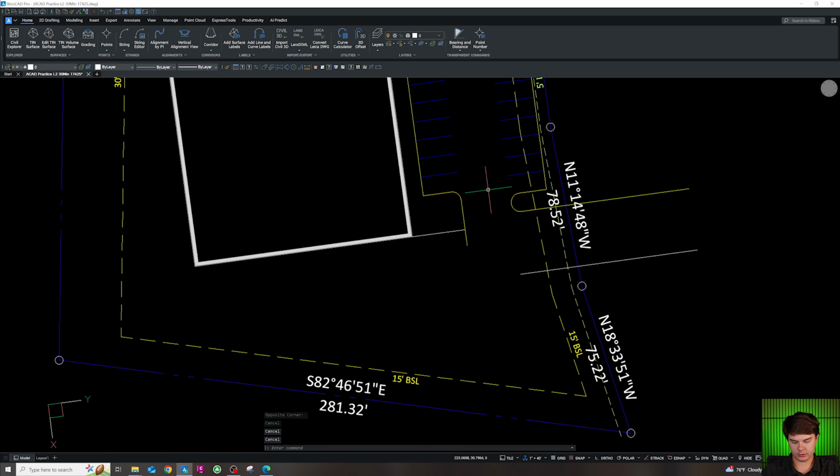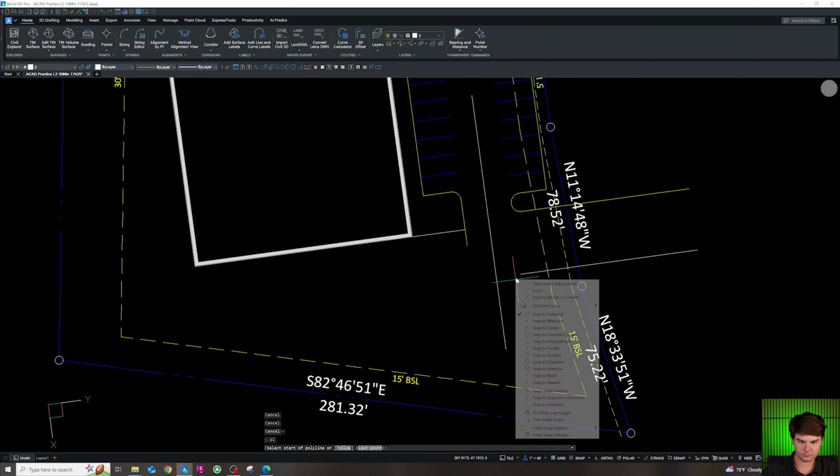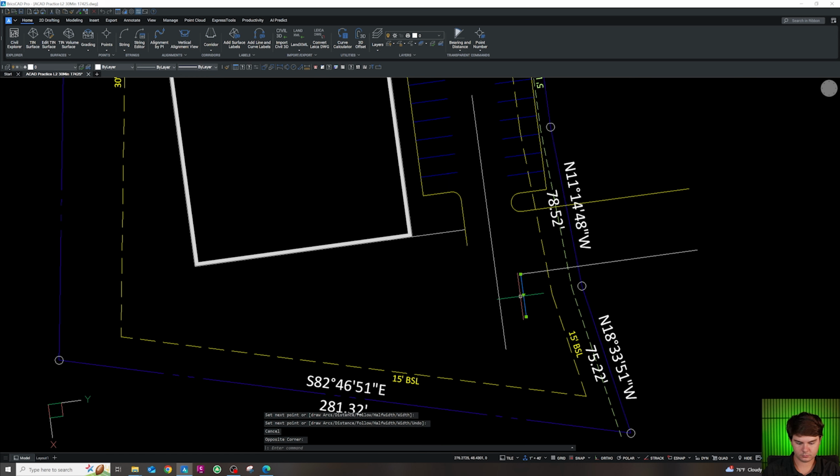It looks like these 4 parkings down here are centered with this drive aisle. So I'm going to draw the center line, extend it down. I get this ortho 18. Offset at 9. 1, 2, 3, 4. Here's our 4 parks.